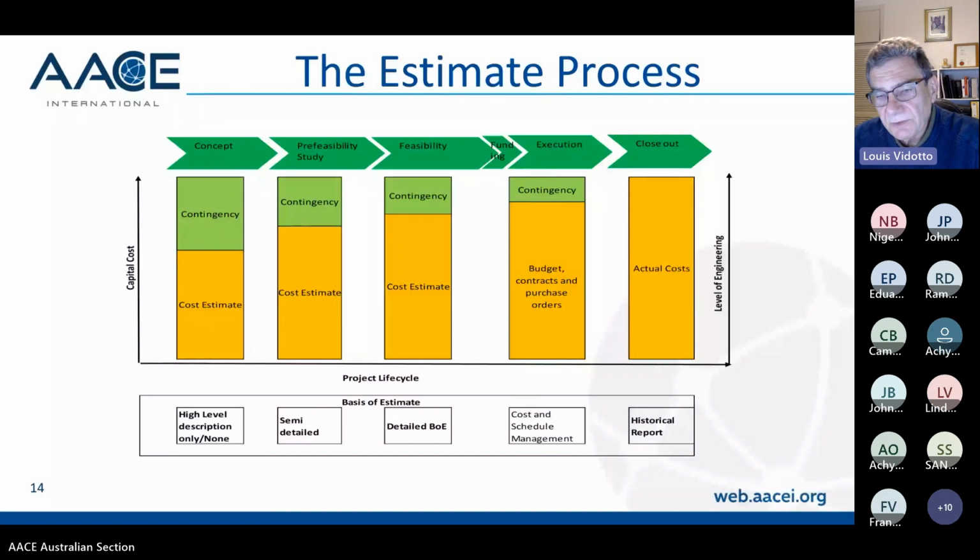And again, one of the things to remember, depending on where you work and who you work for, as an estimator, try and get those actual costs to start to feed back into the cost estimate database to see whether our assumptions were right or wrong with production rates. How many cubic meters of dirt can a scraper crew move per shift? Our assumption was 5,000 cubic meters. What did they actually get on that job, more or less? So that analysis of historical reports becomes pretty powerful to make your estimating better.